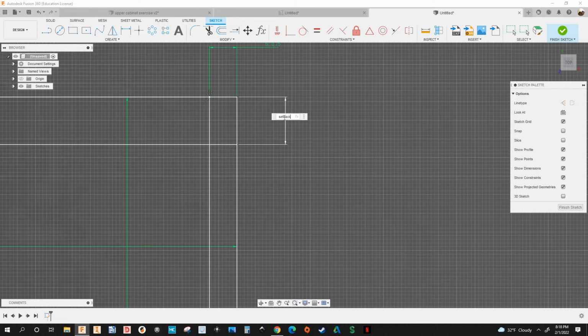But you guys might be thinking, wait a minute, the setback is the same as thickness. Yeah, it is. But sometimes you might have a smaller setback, like a smaller piece that goes in the back, right? A little blocking, so the thickness might be different. That material is gonna be the blocking material, right? If let's say it's not like MDF or melamine, which is true 3/4, right? It's gonna be plywood, so it's a little less. So that's why I created this setback parameter.